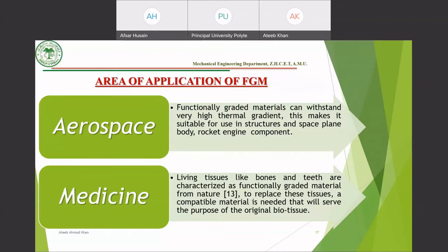Now, this stress shielding effect might be new to you, so I'll explain a little bit about it. This is an effect which causes a reduction in the density of the bone as a result of the removal of the typical stress from the bone by an implant. When you remove a bone and insert a metal implant, initially there was some stress coming from the bone you have removed, which will not be the same as with your metal implant, and usually it is lower than in the pre-existing bone.